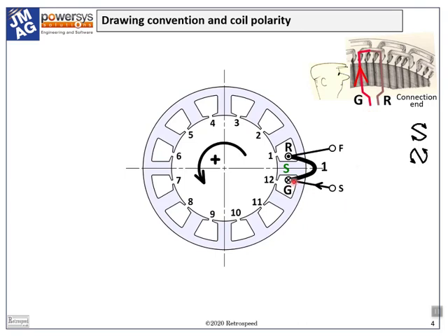If positive current flows in the go coil side, a south magnetic pole appears on the bore of the stator between the coil sides. We can work this out by Fleming's right-hand rule, or the rules of electromagnetism expressed in vectors.